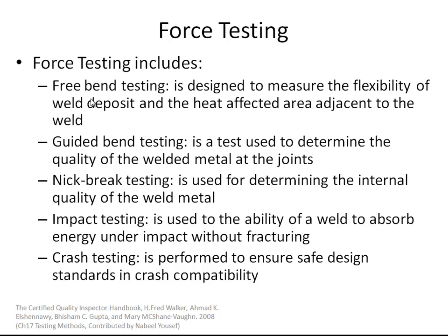The impact testing is used to test the ability of a weld to absorb energy under impact without fracturing the object. It is considered a dynamic test in which a test specimen is broken by a single blow. It's useful in finding out whether any of the mechanical properties of the base metal were destroyed by the welding process. The crash testing is performed to ensure safe design standards in crash compatibility, and as we said before,